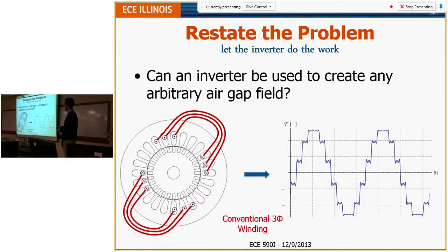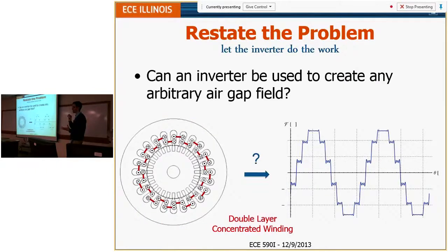This one here, because the windings have to go across 6 slots, you're going to have many coils on top of each other. So the actual size of the machine is going to be like 150% of the magnetic part of the machine. So it's actually really big. This one would be almost a third smaller. So in some applications, that's better. Size is better. But I don't think efficiency.